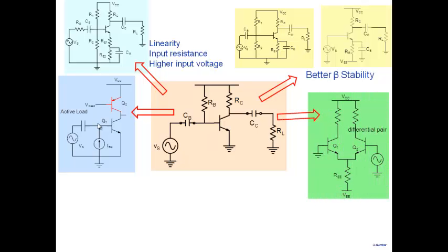Another problem: all these amplifiers that you see here, they use capacitors. Coupling capacitor here, bypass capacitor here. They all use capacitors. And I've talked about it earlier, capacitors are something that you can't make on a chip. Capacitors of microfarads you can't make on a chip, and therefore these configurations that you see here are not suitable for on-chip implementation.